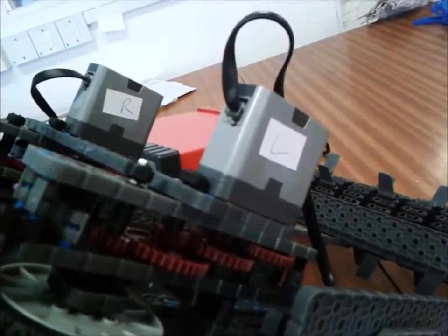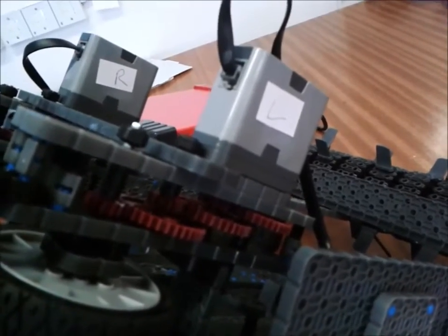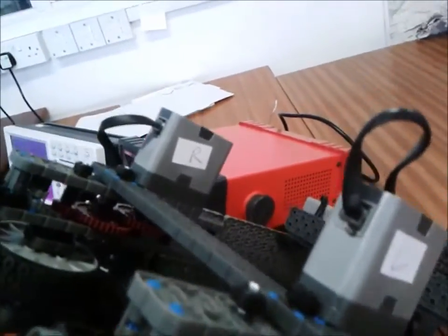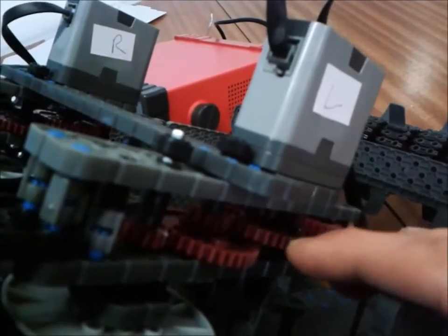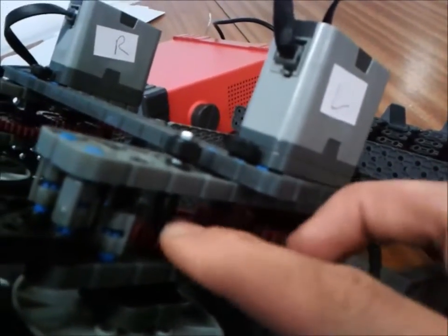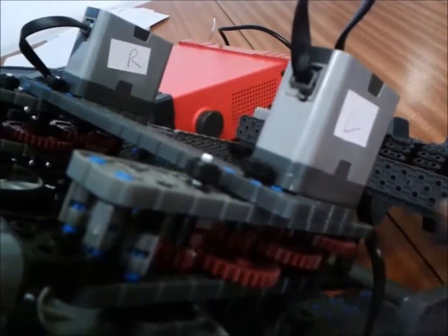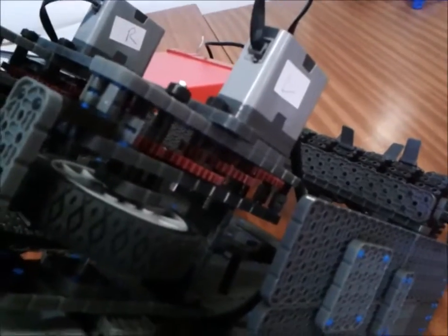It's currently connected to the 9:1 ratio, and it can also do a 27:1 by moving the motor to drive a different gear. So at the moment the motor is driving this first stage, and we can drive this shaft instead, which gives us an extra set of gears for playing around with the 27:1 ratio.